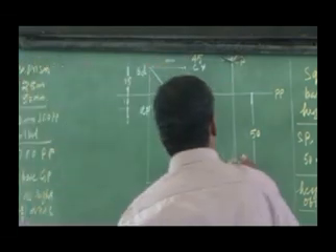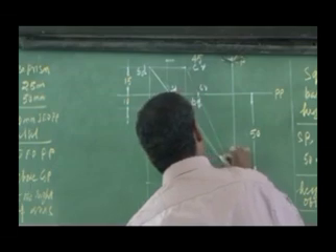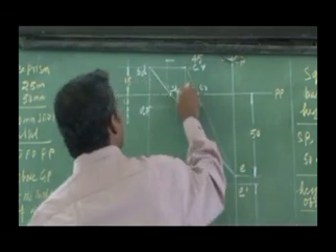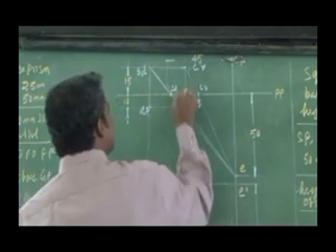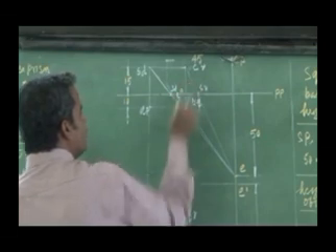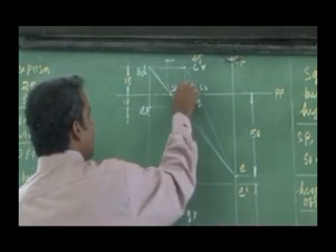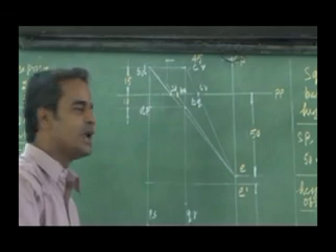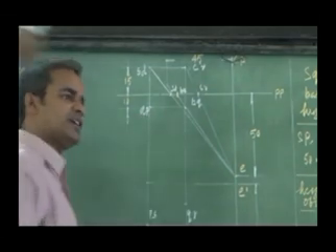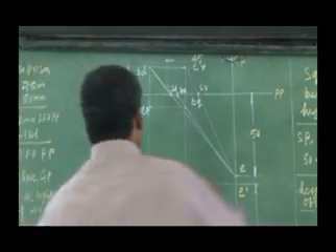So the same visual ray line can be extended in the reverse direction. Where it intersects the picture plane in the reverse direction, that is the intercept of BQ. Similarly, this corner edge, I don't have an intercept directly. I have to extend it in the reverse. That is the difference you have.